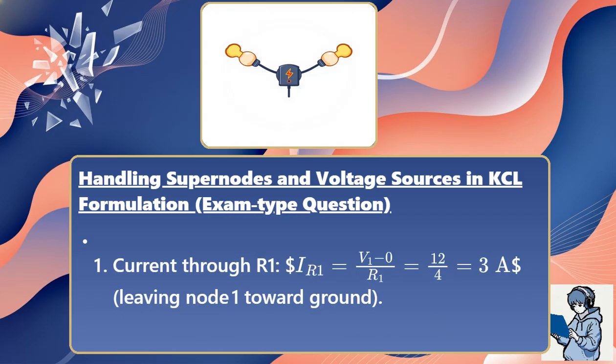Step 6: current through resistor 1. IR1 equals (V1 minus 0) divided by resistor 1, which is 12 over 4, equals 3 amperes, leaving node 1 toward ground.